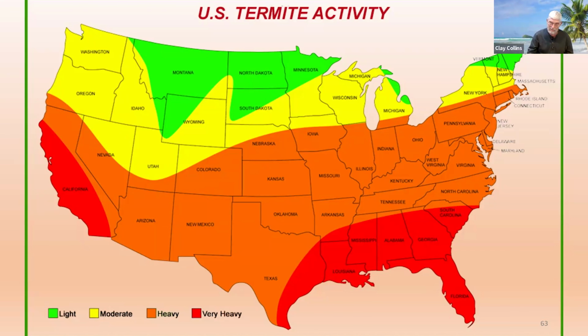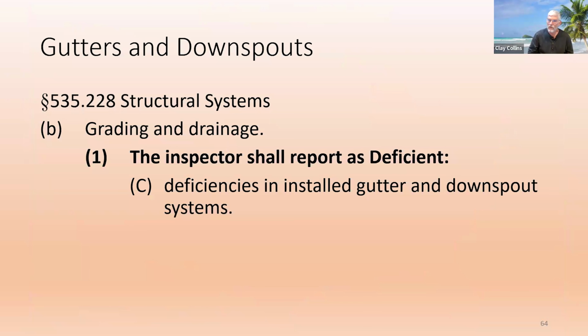So how do you mitigate high soil and poor drainage? Well, gutters and downspouts. Are gutters a code requirement? The code says that water runoff from the roof should extend 5 feet past the foundation. Well, unless you have a 5-foot overhang of the roof, and that simply doesn't happen, about the only thing you can do would put in gutters and downspouts, but that doesn't happen. Frankly, they just ignore the code. The authorities having jurisdiction don't do a thing about it.